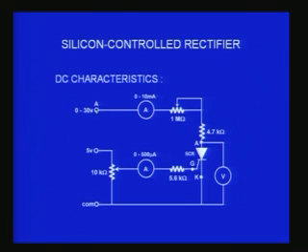So you would find if I keep it at 30 volts, of course 30 volts is not enough to break this SCR. The forward breakover voltage will be some 200, 300 volts. So it will be very difficult to make this conduct with 30 volts, and therefore I have to give a gate current. So now if I move this wiper on the 10k potentiometer, you would find at some current you will have enough current to forward bias that junction. Therefore there is immediately enormous conduction here, and the SCR will be triggered on.